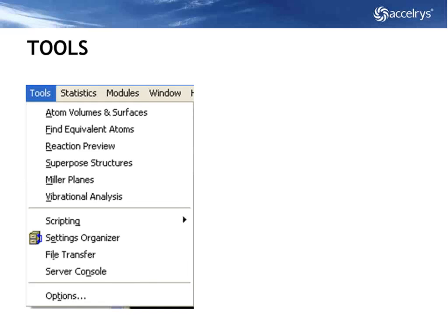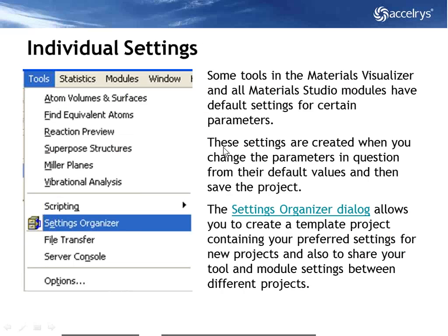Now, what is interesting about that is that then you can take that into a transition state, nudged elastic band, linear synchronous transit, or quadratic synchronous transit mechanism, and start to do iterative calculations on each of those points and say, am I actually converged at a minimum, or am I a long way from that minimum, and how does that work? Okay. You can also customize the settings in Material Studio, so you can save your settings for each module if you have a set of preferred algorithms.